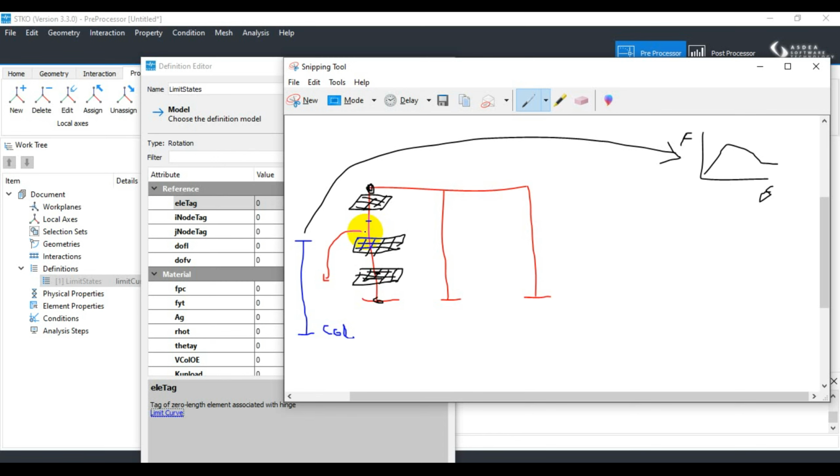If we already have this kind of study performed, then based on the experimental data, the failure surfaces can be formed to define the onset of shear and axial failure of such columns in terms of capacity curves. We can also find that after the response of the column intersects the failure surface, the shear and axial strength of the column begins to degrade at some point due to nonlinear behavior of the concrete.